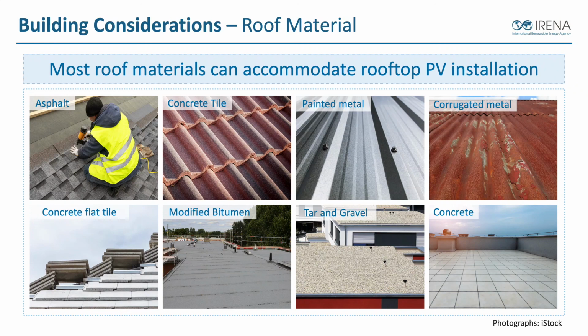All of these different roof types have products on the market to attach to them. Every one of them is going to have a slightly different attachment point or connection to the roof, but there are major solar racking and mounting manufacturers all over the world that make products for all of these different applications. So part of the design is understanding what roof material we have and what attachment product I am going to use in order to put my solar on this building, connect it to the roof, and make sure that it's connected well enough to not blow away, meeting our wind loads and our storm load designs based on our local area.